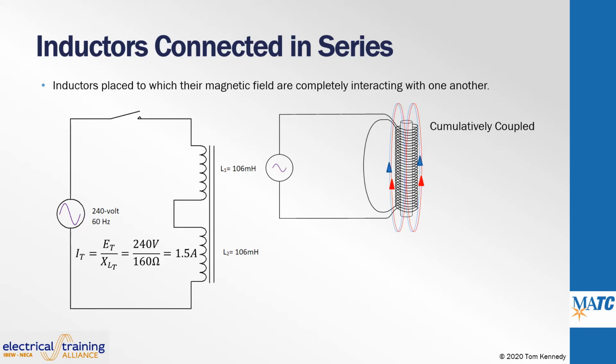Therefore, additional factors of magnetic coupling are required for this type of circuit when the coils are placed near other coils in which the magnetic fields are in the same direction. The term cumulatively coupled is used when the magnetic fields become additive or they accumulate. To calculate the total inductance in this circuit, an additional factor that includes the coefficient of coupling of the two coils is included and multiplied by the number of coils connected.